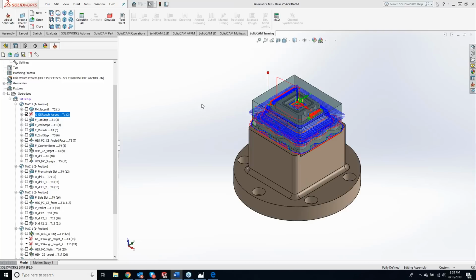What we're finding with a lot of these machines is some machines like line segments and point to point, and some machines run better using arc movements. A lot of the newer machines, and Greg, correct me if I'm wrong, are more proficient and faster using line segments versus arcs for computing the data. Yes, that's correct.